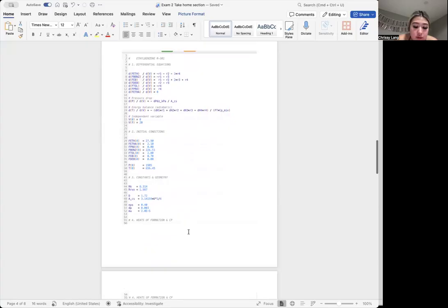For question 4, I modeled the first packed bed reactor, R301, in the ethylbenzene production process using Polymath and then compared my results to the stream tables found in the textbook appendix. The reactor carries out 4 reactions involving benzene, ethylene, ethylbenzene, and byproducts like diethylbenzene and other hydrocarbons.